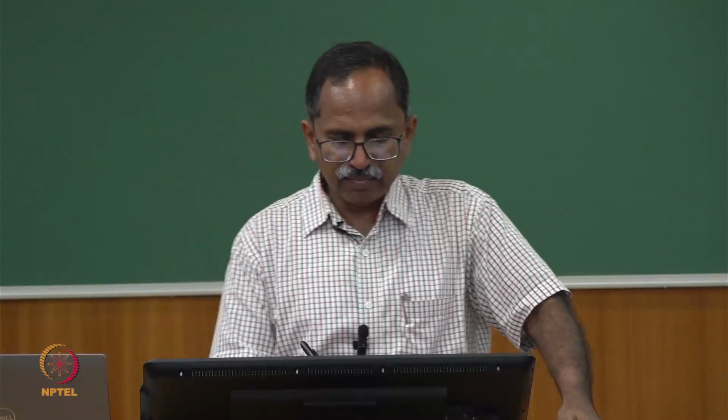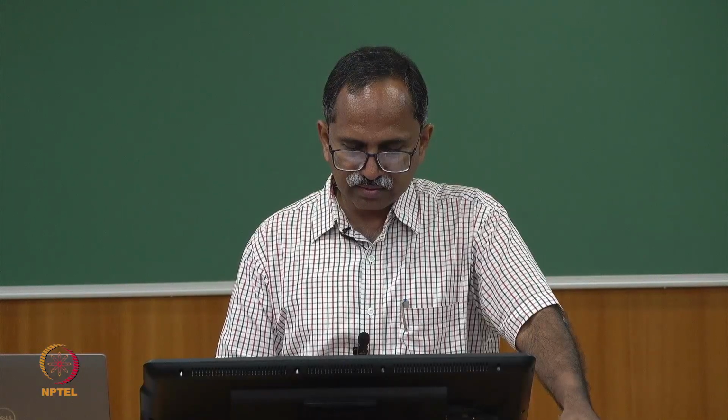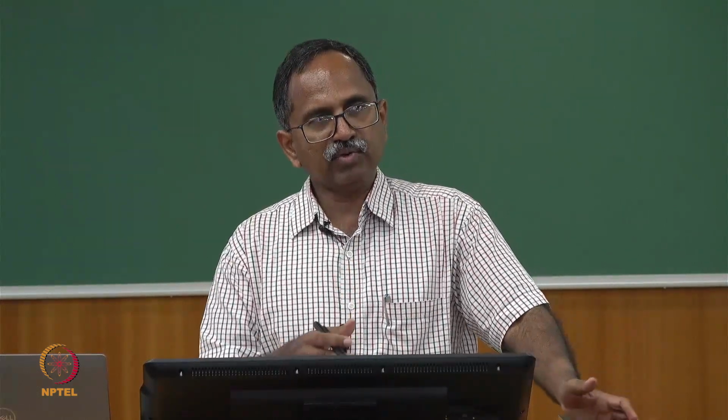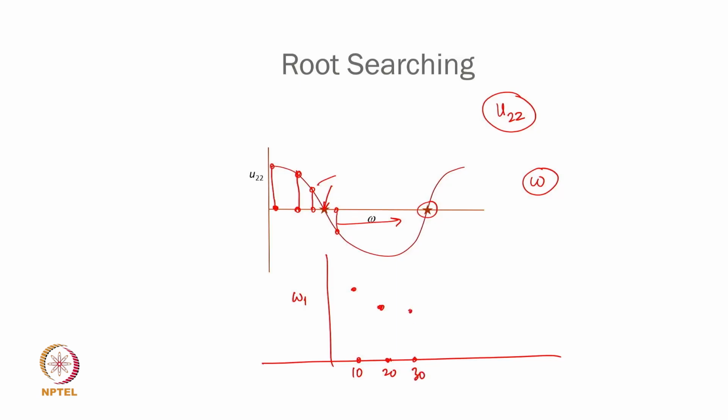Now what can be done by you is that same system, if you discretize it into, let's say, 10 segments, find out what omega 1 is, maybe you will get this. Then instead of 10 segments, that entire gearbox you discretize into 20 segments, reevaluate omega 1, maybe you will get this value. Discretize into 25, 30 elements, you will find that with a larger number of segments, this omega 1 will stabilize and approach a constant value.